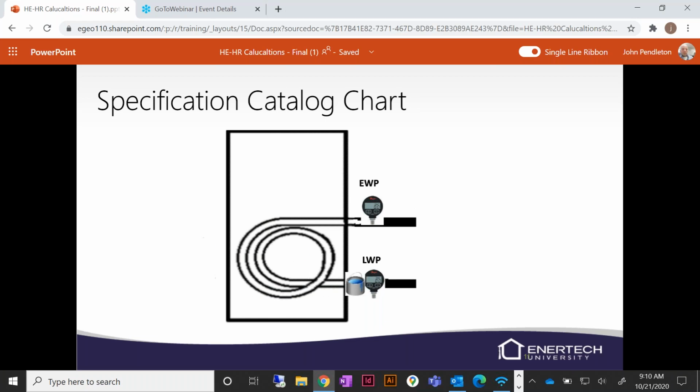If you ever have a lower pressure in than you do out, then you've got your flow reversed. Normally there's stickers on the cabinet that'll tell you what the source in and source out is, but there's been a few times when I've seen the factory get those stickers flip-flopped. And so if you think that it's swapped, look in the IOM.